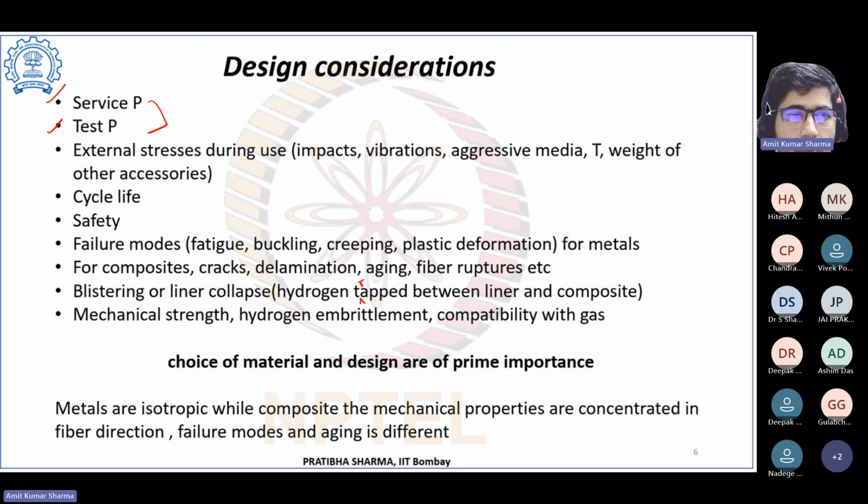So the test pressure is 1.5 times higher than the service pressure. Service pressure is your operating pressure, or the maximum pressure that you can have in your system. The cylinder will be tested at the test pressure, so this bottle can store up to this pressure without failure.